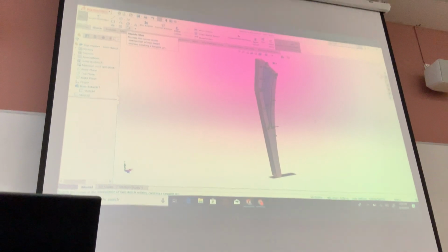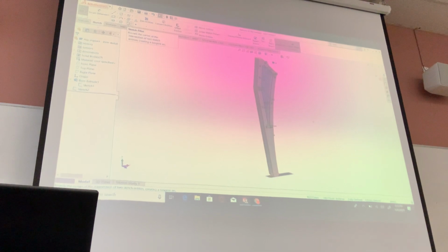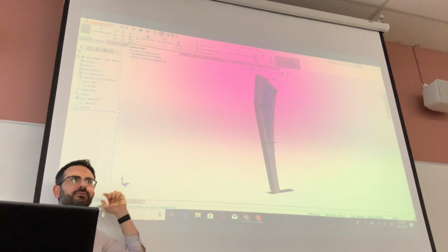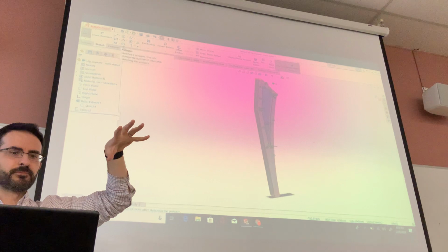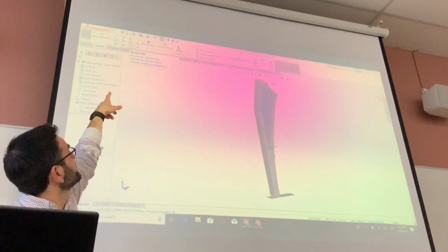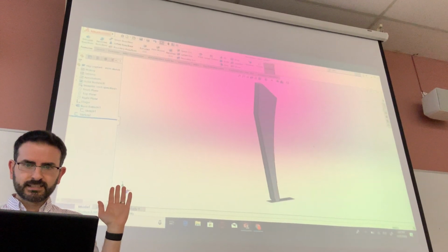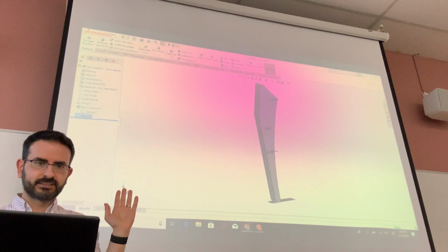There are two ways. You can create a fillet on the sketch or on the 3D feature. What I'm doing here, I'm creating the fillet on the sketch. It's just a choice. I think you get the same result basically, but this time I'm doing it this way. Later I'll do it on a feature. So if you're doing it on the sketch, you do it from within the sketch editing mode, and you just use this command here that says sketch fillet. Because I've already done it, I'm going to undo, and now I'm going to move to, again, extrude cut this new sketch.